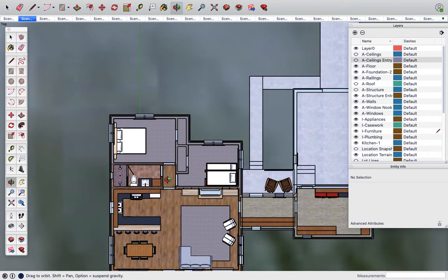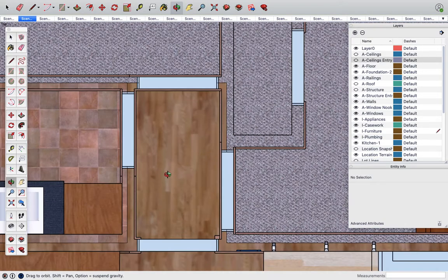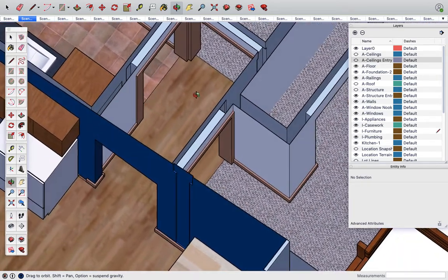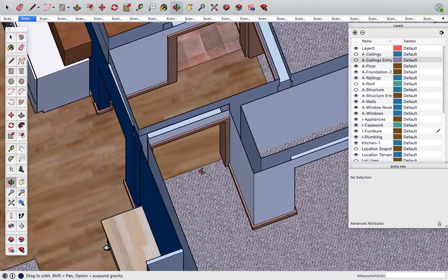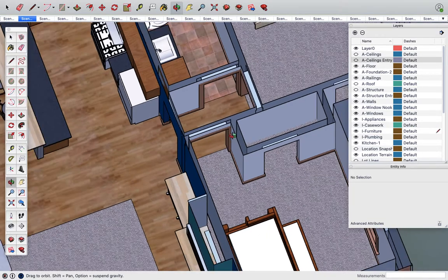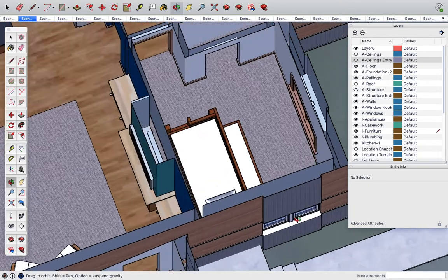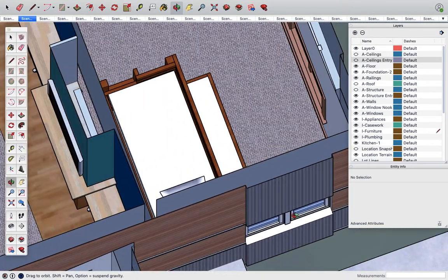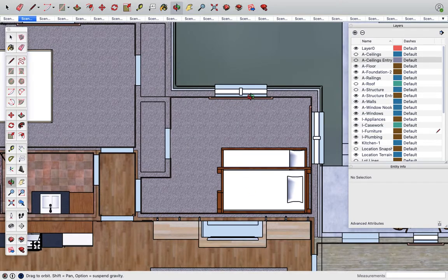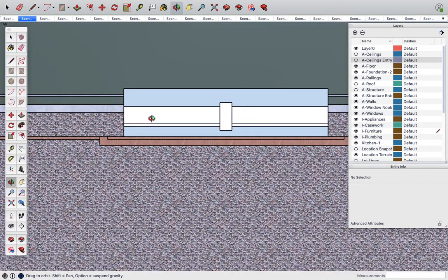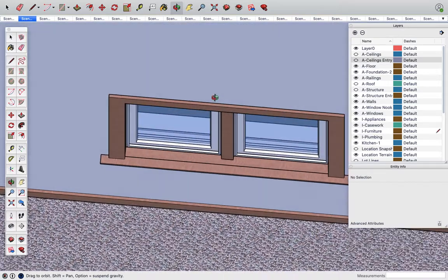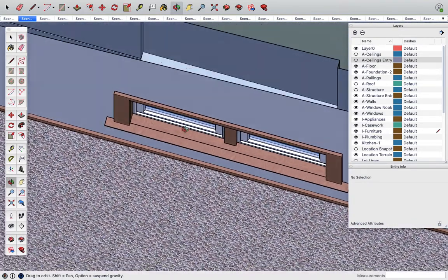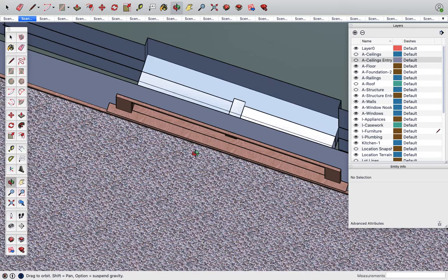Problem is, you don't see the window or the door openings here. What we're seeing is actually the top of the door frame. Okay, and you want to have a slice through the door. You want to have a slice through the windows, which are here. So again, if I do Command 1 top view, it kind of looks like you see the windows, but you're really not. You're seeing the top of the window from above, right there.